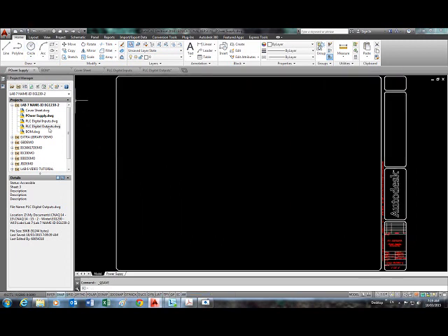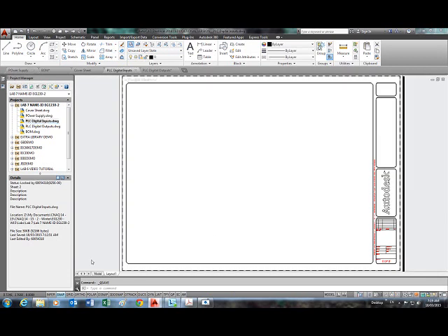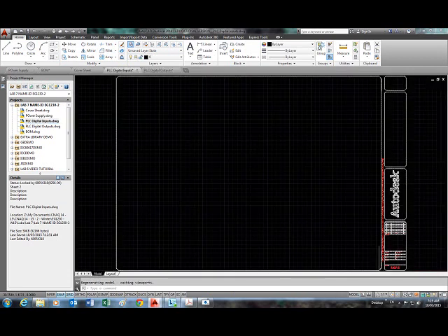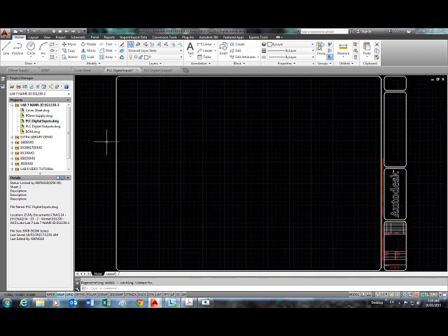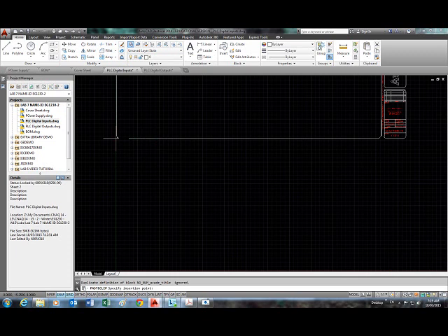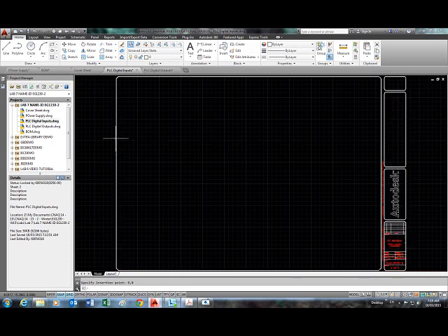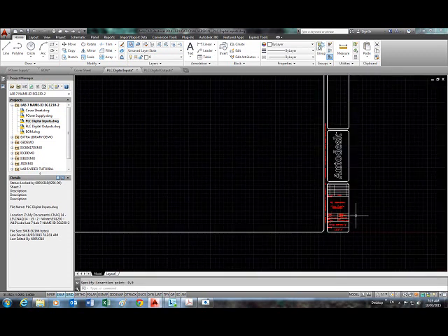Make sure to save again periodically. And instead of having to do each one of them individually, what I'm going to do, and I suggest this is a good idea, is to click on the title block, and once you see the handles and everything is sort of grayed out or highlighted, press Control C for copy, go to the next drawing, choose the title block, delete it, and then paste and type 0,0, and you need to only change a few things.